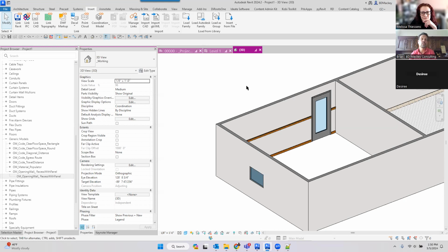So we have to know that, and we just have to use communication to start telling people, cool, if you edit a design option, you're done. Make sure you synchronize. So if somebody else sees that design option I need to get into, or send a Teams message out to everybody in there, hey, I'm editing design option X. If you need anything, let me know, and they can tweak it for you. But that is just a limitation of design options and groups as well. Once you edit that group, you take ownership of that group. And just like when you finish editing a group or you finish editing that design option, you are the owner, so you have to go synchronize to give up your rights to that.